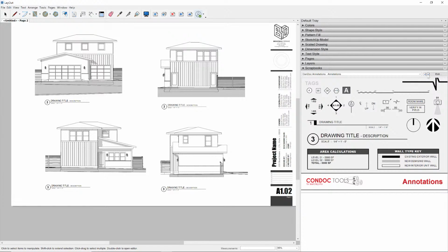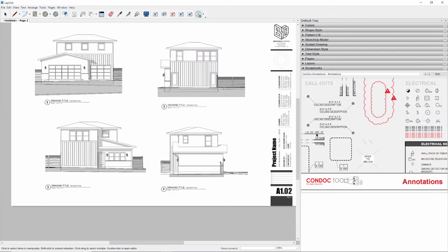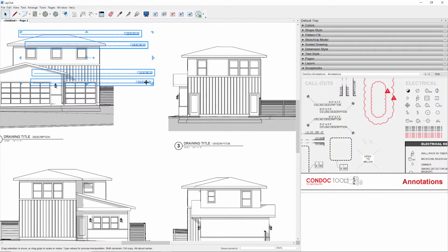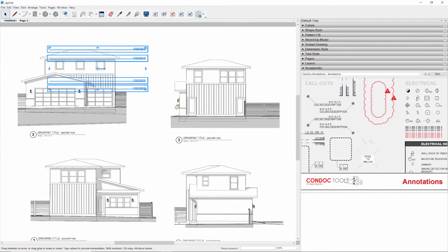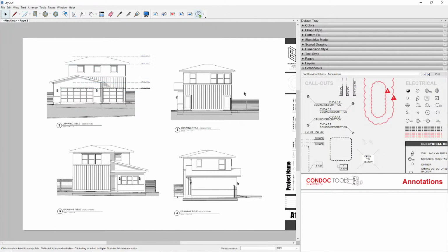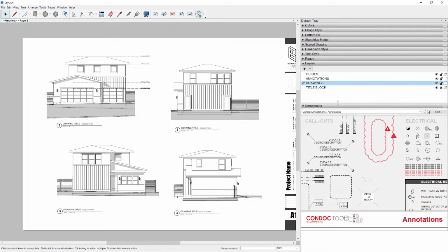On this one, you could go to the next page and perhaps you want some different level markers. So we'll go maybe top of roof, top of plate, so you can have all that stuff sorted out. And then it's easy enough to just grab these, right click, align to the right, shift nudge. When you hold shift with the arrow keys, it nudges 1/4 inch. Let me say this too, I always forget to do this, but like the layers.